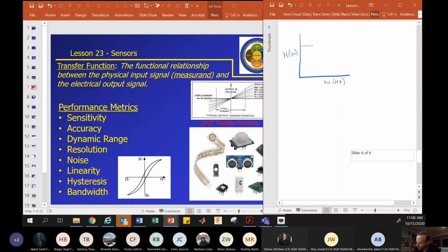And so this would be a typical looking transfer function for a first order system. And that's what you might get for a typical sensor. Something like an accelerometer, a second order system, might have a bump here. So what this is saying is that when frequencies are low, and this is usually 1 here, you want the output to be matched to the input.